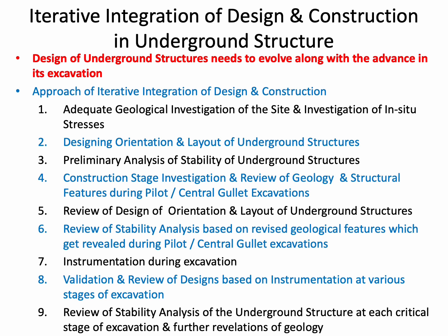Instrumentation during excavation. Validation and review of designs based on instrumentation at various stages of excavation. Review of stability analysis of the underground structure at each critical stage of excavation and further revelations of geology. So all these 9 steps comprise the iterative integration of design and construction in underground structure.